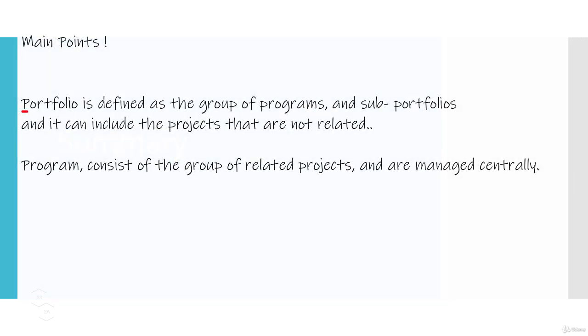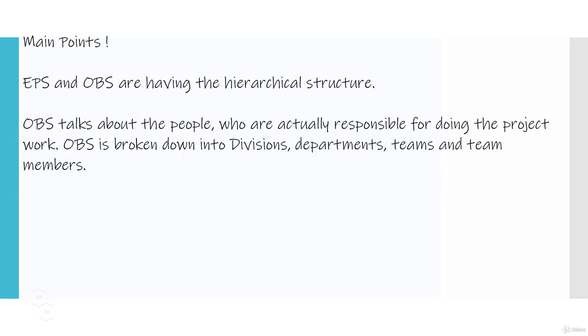Next, a portfolio is defined as a group of programs and sub-portfolios, and it can include projects that are not related, I mean projects that do not have common characteristics. We have also discussed that a program consists of a group of related projects and is managed centrally. Also, you have learned that Primavera P6 is the project portfolio management application mainly used for project schedule management. We have studied about the EPS or Enterprise Project Structure, and OBS or Organizational Breakdown Structure.